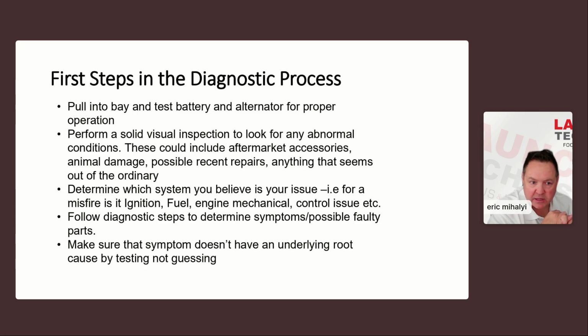Solid visual inspection. Can't tell you how many things I've found with visual inspection, especially back when I was a dealer tech. Car comes in, it's got a bunch of weird electrical problems. Look in: new aftermarket alarm, trailer hitch wiring, obviously audio equipment, right? Looking around for signs of animal damage. You open up the hood of a car and there's nuts everywhere. Obviously, there's some kind of a rodent type animal living in there.